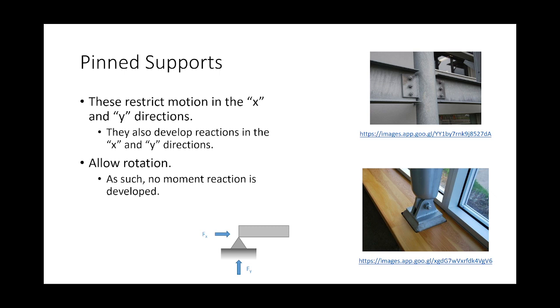the flanges, do y'all know what I mean by flanges? If you have an I-beam, the top and bottom plates are the flanges, and the middle plate is what's called the web, okay? The idea is that for an I-beam, the flanges carry a significant component of the moment, but the web is what carries the shear or the vertical forces. So since this connection is only transmitting those shears and not those moments, we would idealize that as a pinned support. Does that idea kind of make sense?